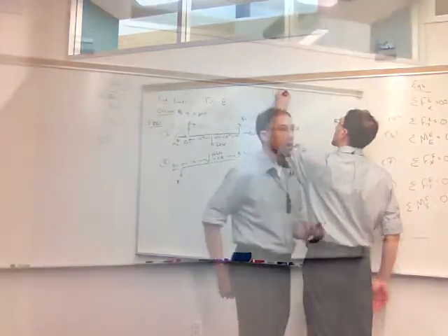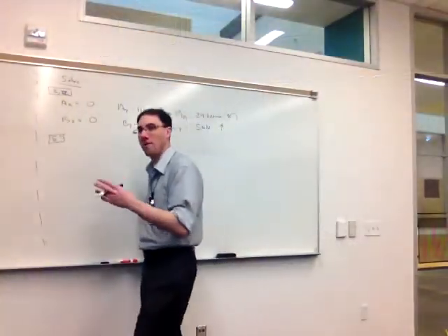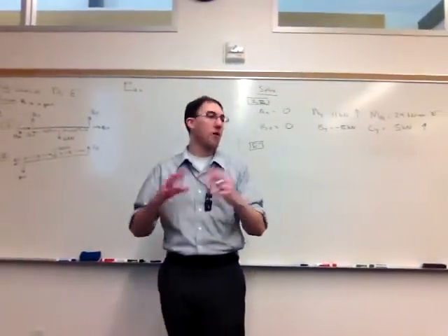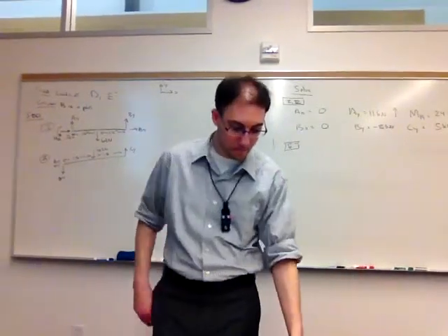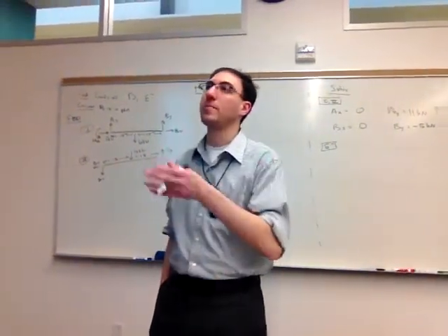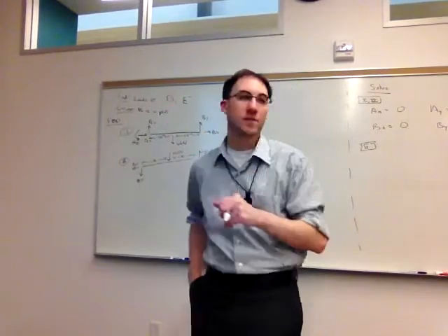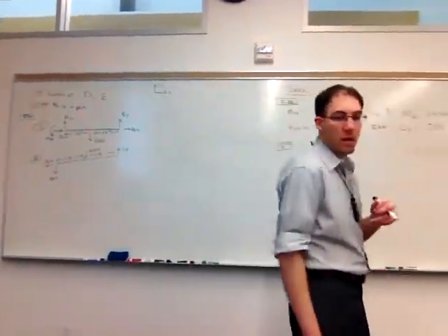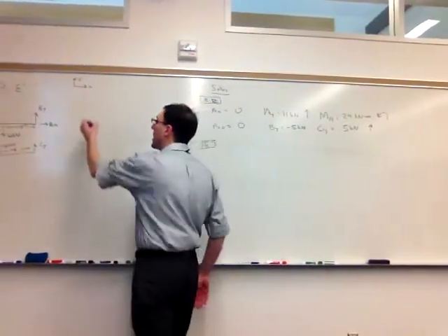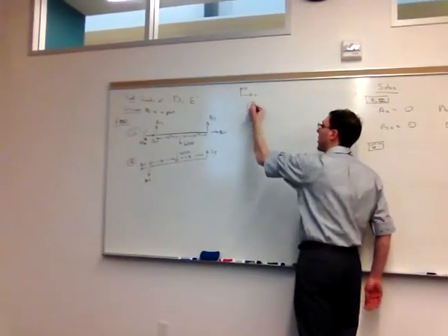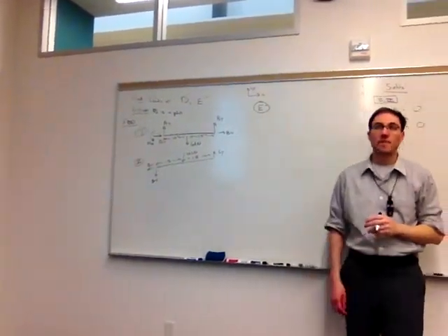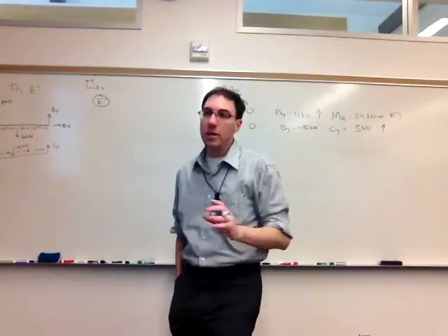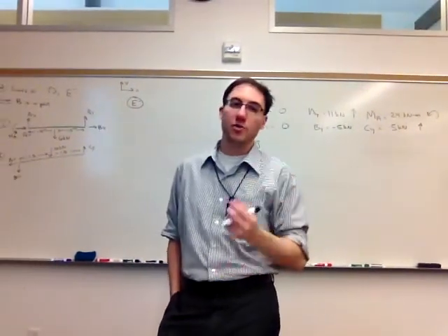So now we're ready to go and make our internal pictures, now that we know all of our external reactions, I'll call them. I'll start next. We need both D and E just to the left of the 10 kilonewton load. Let's start with E. I'm going to call it E minus because it's just to the left of where point E is located.